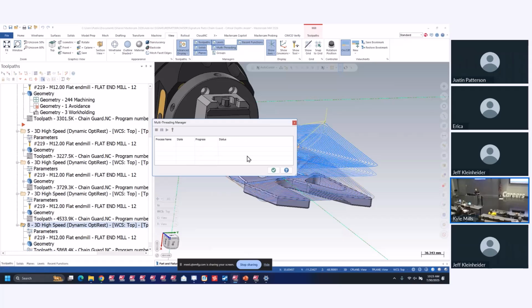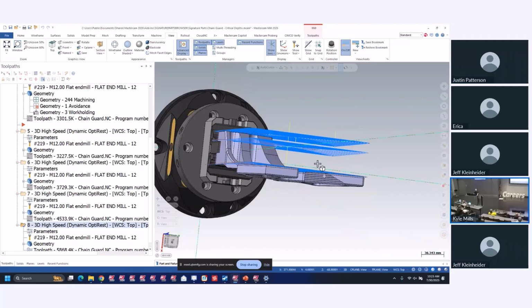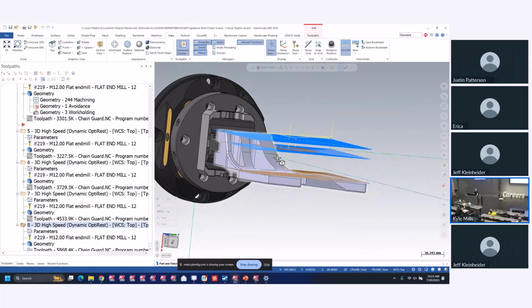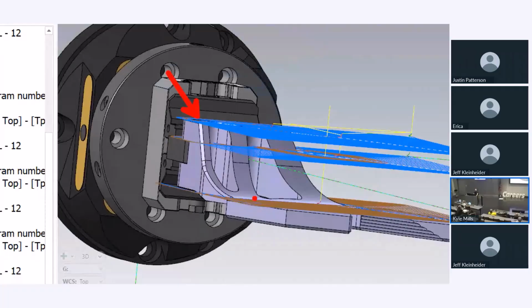Now you'll see that I've recalculated that. Instead of having the one pass there, I have one at the top flat and one at the bottom flat. Nice and easy without having to turn on my step ups. If you were trying to rough something out really fast and didn't want to worry about going up that angled wall with step ups, you could quickly put this on and still include your flats without having to play with your step down, which is a great addition in my opinion.